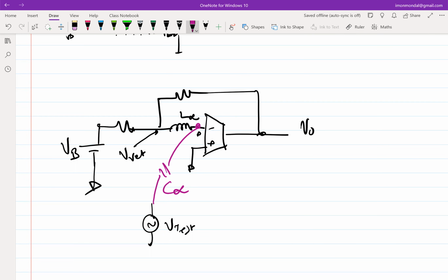These are a few of the standard practices that we follow to figure out the loop gain while not disturbing the operating point under DC condition. So here the feedback is setting the DC, and then you optimize your circuit. The first time you put everything in feedback, things may not work out. Maybe some transistor is in saturation, some in linear, some in cutoff. Then you go back and debug the circuit with the feedback in place. Don't make it an open loop connection and debug, because your circuit ultimately will be put in a feedback mode.